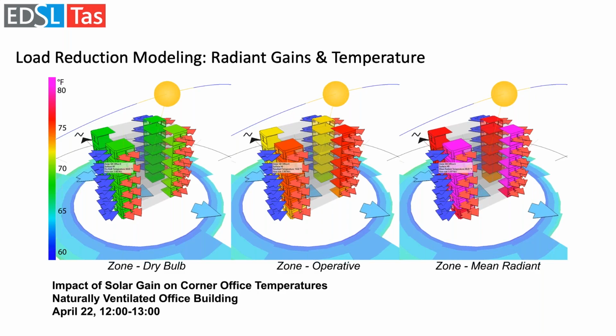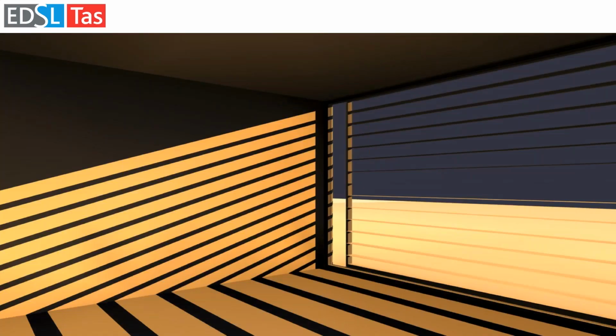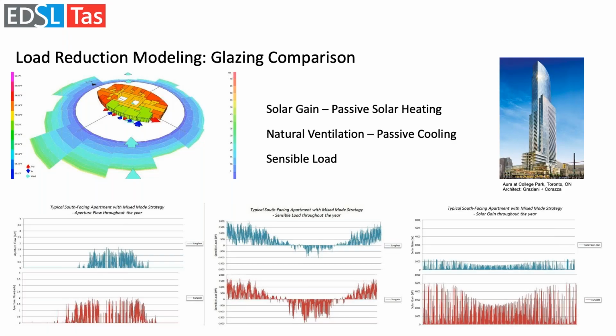And again, all this is just doing passive analysis at schematic design. And when you've defined shading schemes for your building that work for solar and natural ventilation, you then consider the internal light implications of that. So there are some ray tracing simulations that are possible in TAS to do these interior shadow simulations. Building up to larger projects, but maybe just a typical floor, changing glass types for the facade, impacting on the lower right hand side.